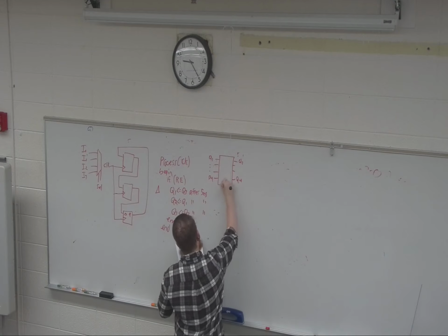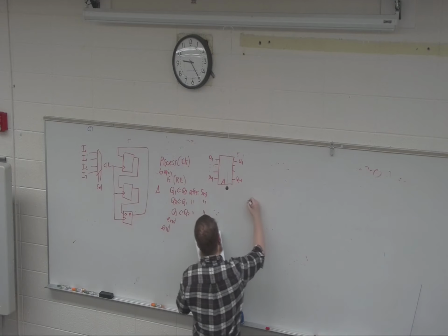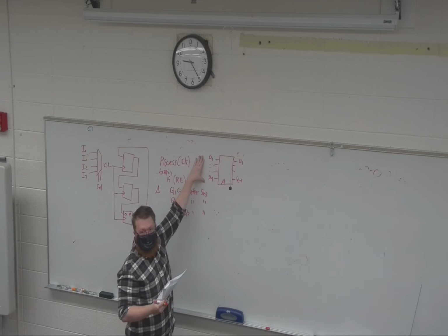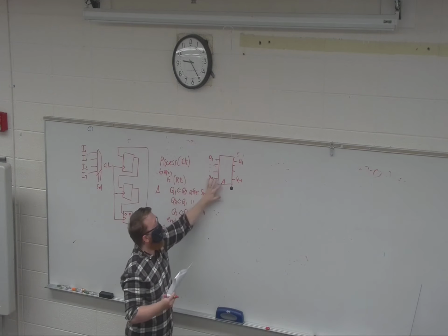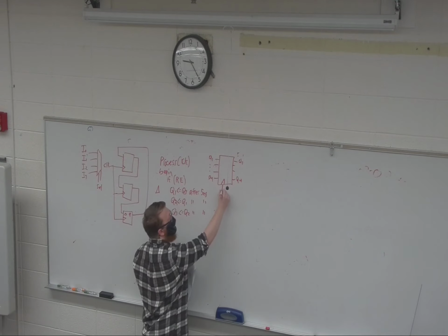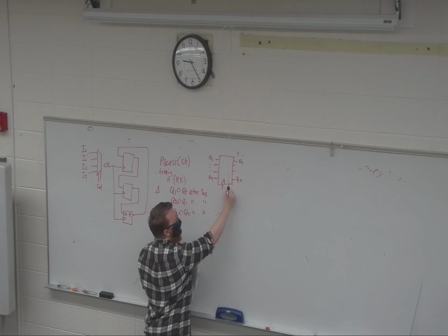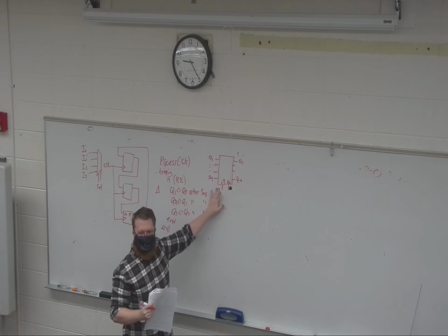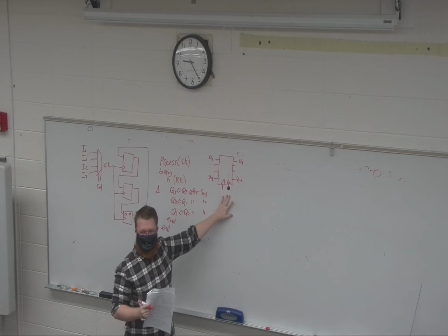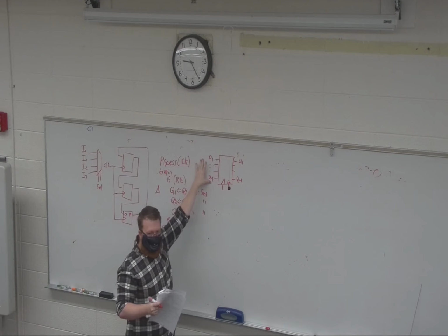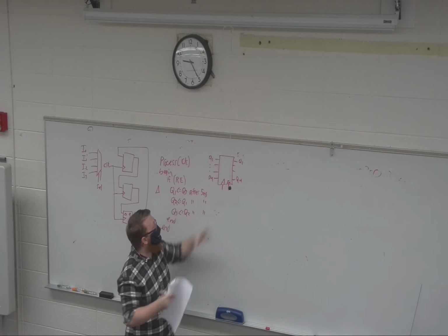And it's going to be clocked. So here, I want this memory on the clock edge. And I'm probably going to build an enable for this, because I don't necessarily want to do it on every clock, I just want to do it when I tell it to. Right here, I'm just going to write this process on clock, if it's the rising edge, and I'm going to start with